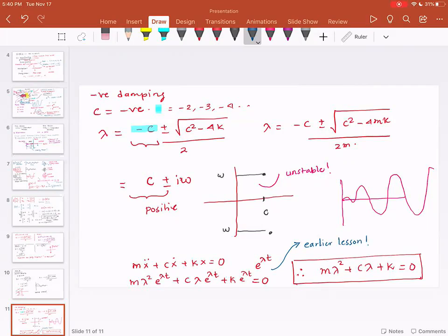And then we tried to solve the equation again here as this quadratic equation, and we obtained the exact same results. Whether you obtained them in the state space form or the first order form, they mean the exact same thing: you have eigenvalues that are purely imaginary, which means zero real part. They are simply stable. If the eigenvalues have negative real part, these are asymptotically stable, and the eigenvalues that have positive real parts are unstable.